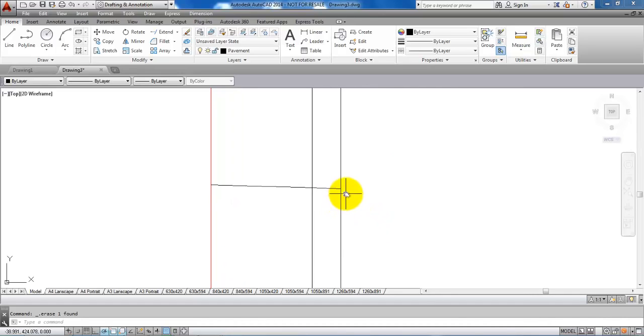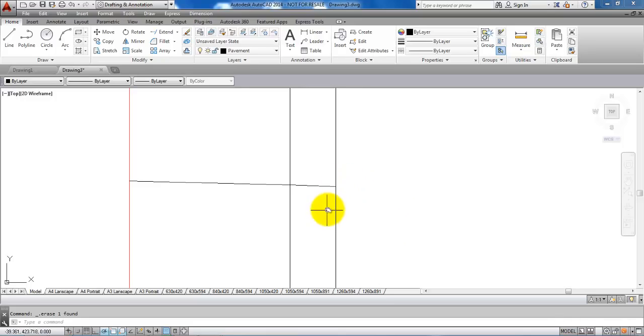And then the next part is to add a slope right here, which will connect to the existing terrain, and I want a slope of 1:2, meaning that every time I move down 1 unit, I have to go in the horizontal direction for 2 units. So again, I will type in L for line, just type in 1 meter and hit enter, and then 2 meters in the horizontal direction. And now we can just connect it here, and delete this line and also this one right here.